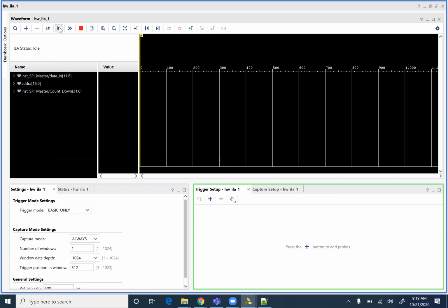But you might build an FPGA system where part of the FPGA is at 100 megahertz, part of it's at 400, and part of it's at 20, and maybe some of it's like 20 kilohertz, right? You might have different speeds, and the debug cores want to know which clock domain they're in. In the case of this, it's really easy. There's one clock domain, you're not going to screw it up. Just be aware that going into the future, these debug cores get more complicated.